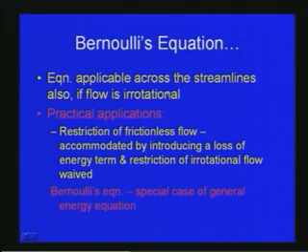Now, as we have already seen, the equation is applicable across the streamline also if the flow is irrotational. We have derived the equation along a streamline, but it can also be applied across streamlines if the flow is irrotational. We have already seen what rotational flow is as distinct from irrotational flow. For irrotational flow, Bernoulli's equation is applicable across the streamline.